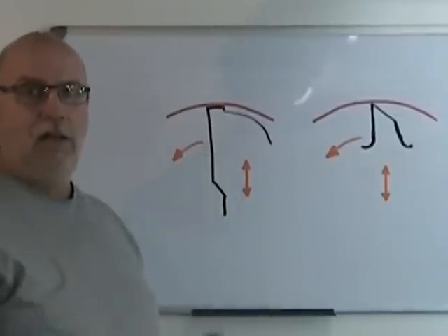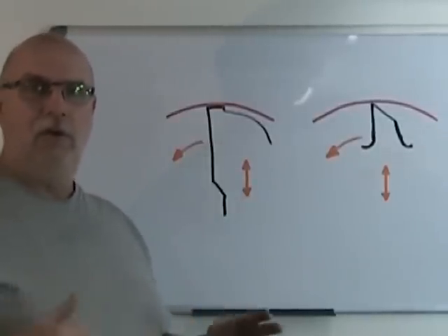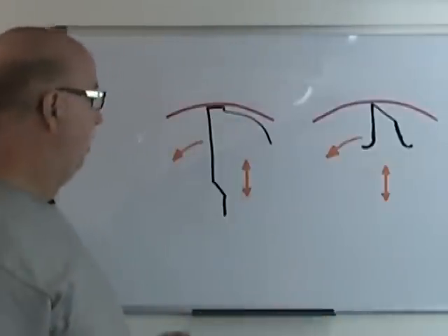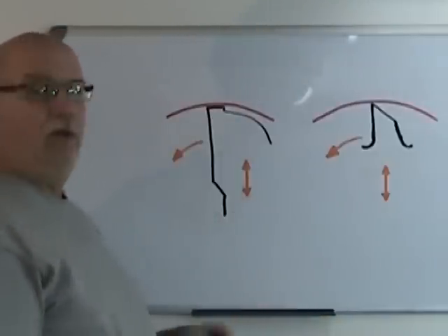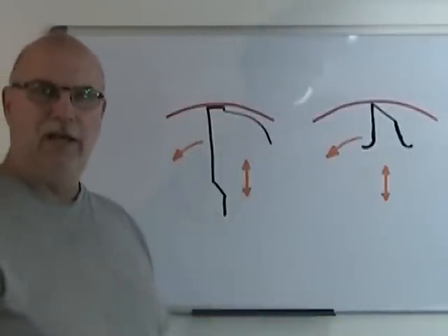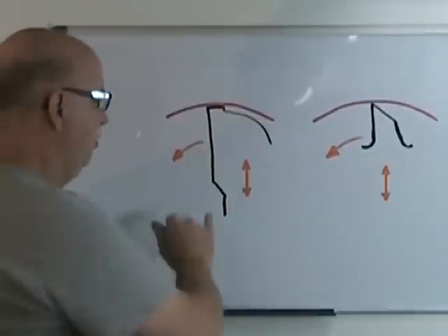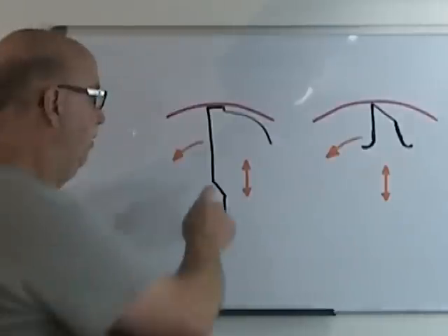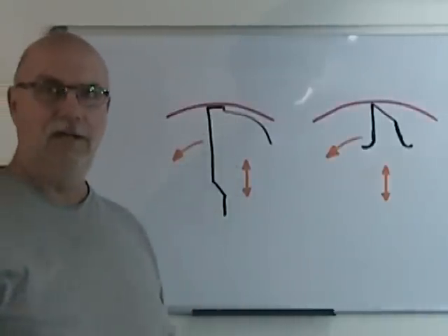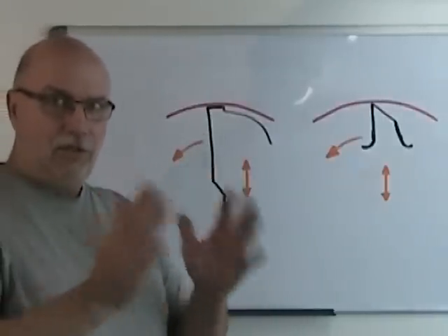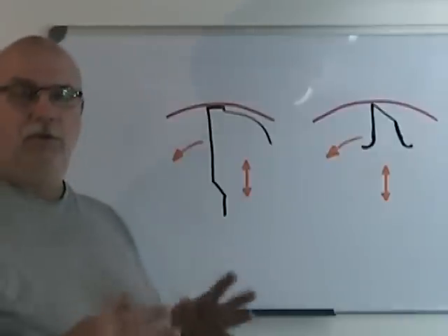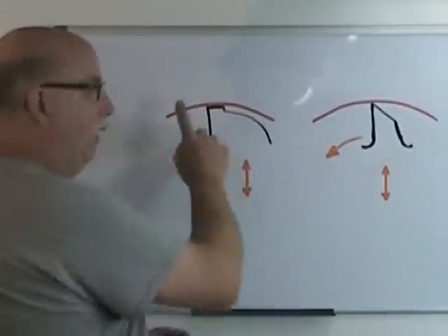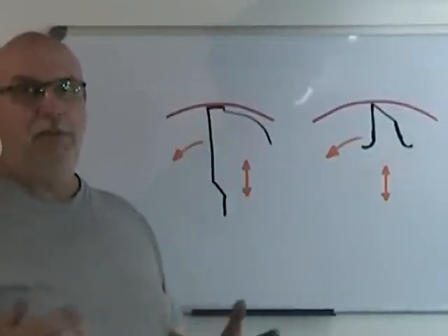But when we pull the drill out or insert it into a hole to go back to the bottom to keep on drilling, well, we often hear a little bit of chatter. And that's because as soon as the chisel edge isn't doing its job of keeping things aligned with the angles of those cutting lips, keeping everything tracking nicely, well, the drill goes to where it naturally wants to go, and that means that one of the two edges of the drill is probably going to be rubbing.